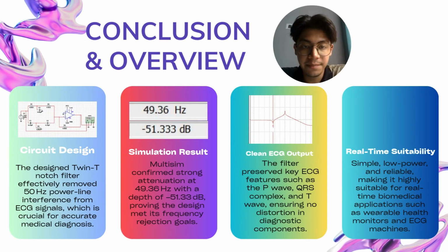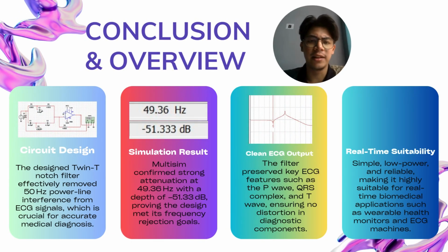To sum up our assignment, our project focused on designing and simulating a bandstop filter, specifically to address the issue of the 50 Hz power line interference in ECG signals. This type of interference is very common in medical diagnostics and can distort critical waveforms. So we designed a circuit that counters these issues. First of all, for the circuit design, we designed a 2nd-order notch filter which effectively removed the 50 Hz power line interference from the ECG signals, which is crucial for getting the most accurate medical diagnosis.